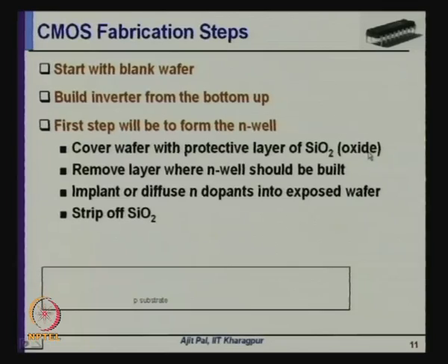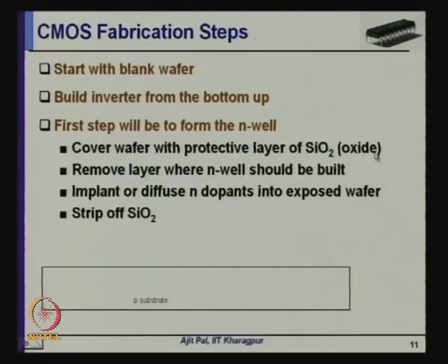Whenever you are passing oxygen, then it is called dry oxidation, then a thin film of silicon dioxide is created. On the other hand, whenever you will be passing the water vapor, then a thick form of silicon dioxide will be deposited, but its quality will not be very good. It will be a little porous type, and it is called thick oxide silicon dioxide.